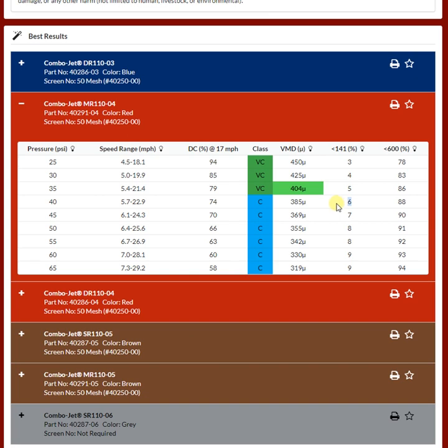With some more restrictive chemicals, you want to be far below that, whether it be 5% drift or less, or some being even sub 2%. Nonetheless, for glyphosate, being within 10% is pretty reasonable. At this point, we're at 6%, which is a pretty darn good place to be in terms of drift, especially given we have a pressure range that we can drop to reduce that driftable fines more.